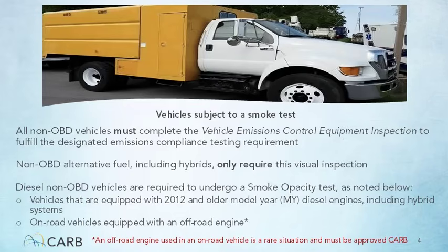As part of a vehicle's emission compliance test, the smoke opacity test is not required for a non-OBD alternative fueled and alternative fueled hybrid. The smoke opacity test is only required on vehicles that contain diesel or diesel hybrid engines. Clean Truck Check requires all diesel and alternatively fueled non-OBD vehicles to complete the vehicle emissions control equipment inspection in addition to the smoke opacity test, to fulfill the non-OBD vehicle emissions compliance testing requirement.